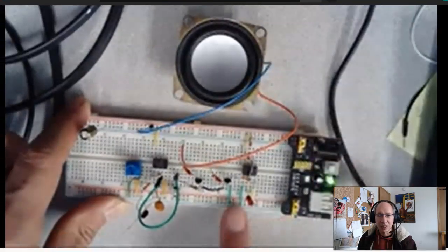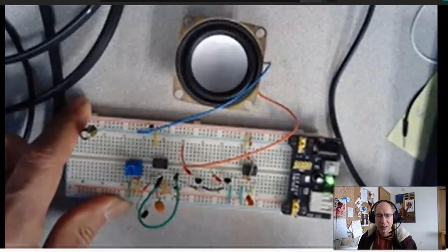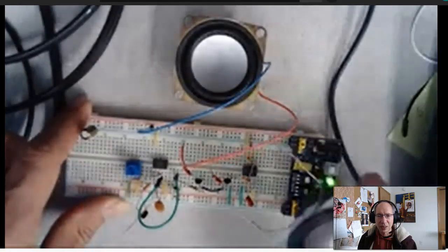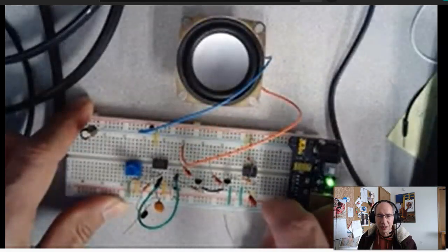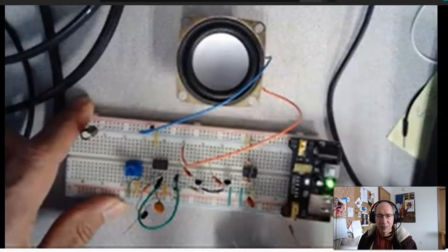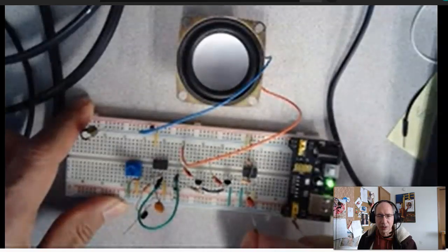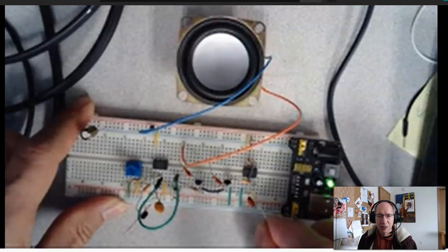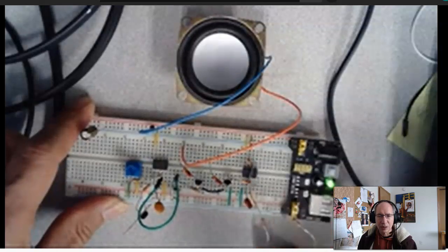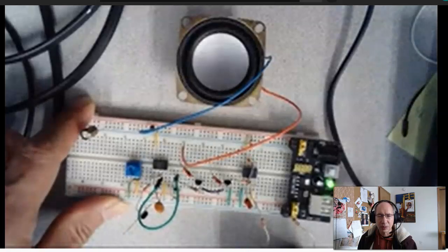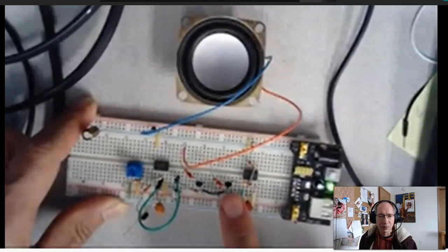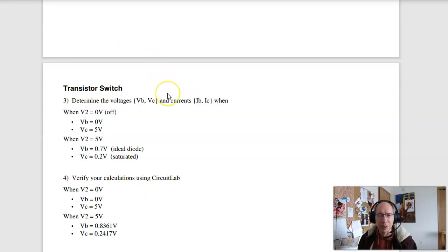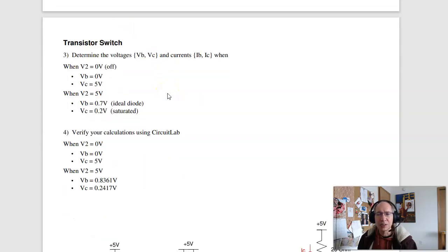So this is my power supply. There's my 555 timer. If I take a speaker, like this guy, with 200 ohm resistors connected in series, take one to ground, the other one to the output, and find it. The output is really quiet. Instead, if I use the transistor as a switch, that's what this one is. That transistor switch will come up in just a second. So the circuit with the speaker and 200 ohm resistor is really quiet.